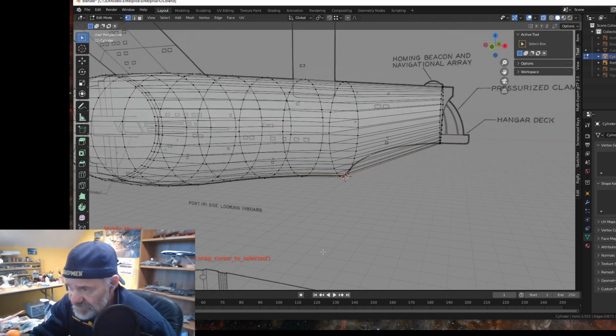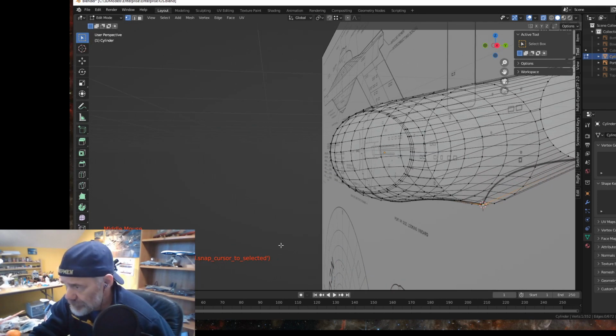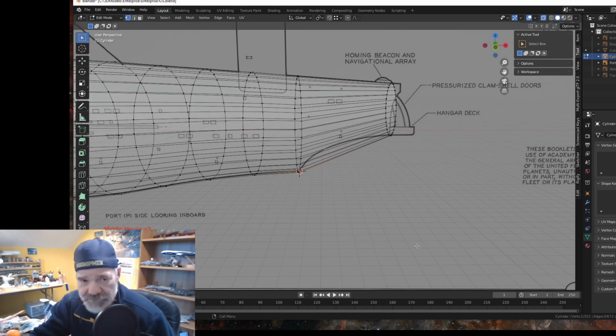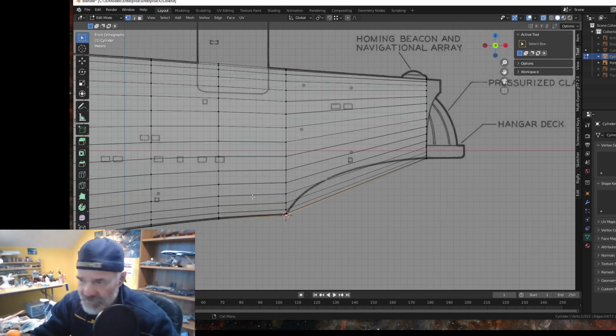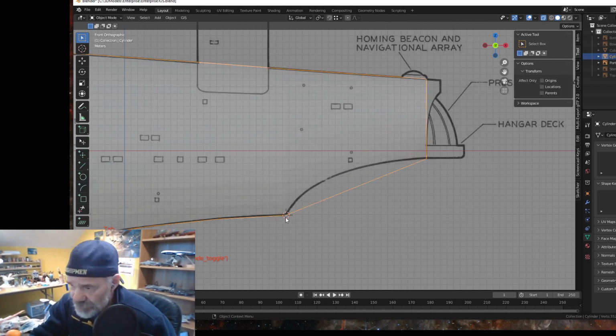So it makes our 3D cursor show up at that spot, because when you add a new object, it always adds the object where the cursor is. Alright, so tilde F, get that front view again. Now I'm going to get out of the edit mode, and with our 3D cursor here, I'm going to Shift A,